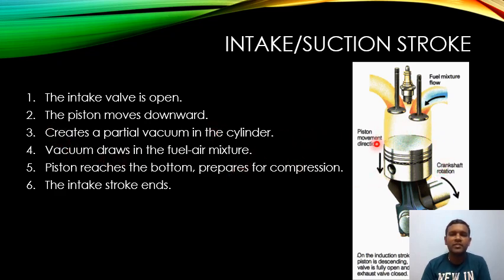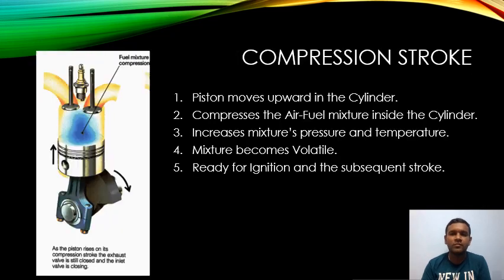The piston is first at the top dead center and moves downwards towards the bottom dead center. When the piston comes down, this creates a partial vacuum in the cylinder, and this vacuum draws the air-fuel mixture into the cylinder. The piston reaches the bottom of the cylinder and prepares for compression. This ends the intake stroke.